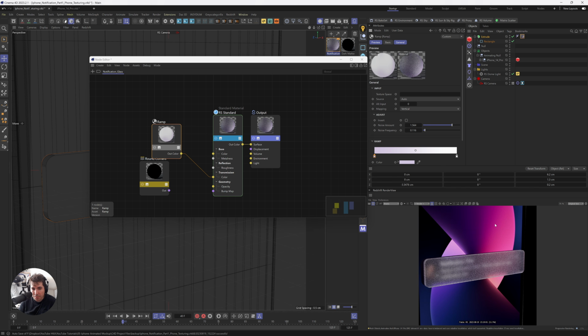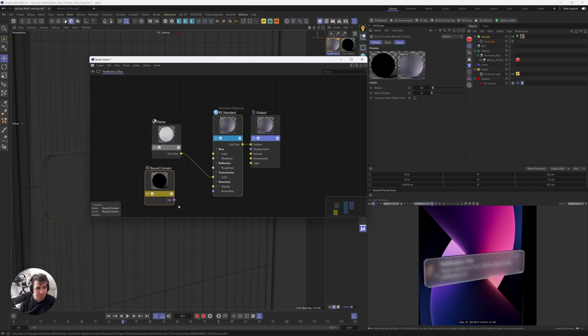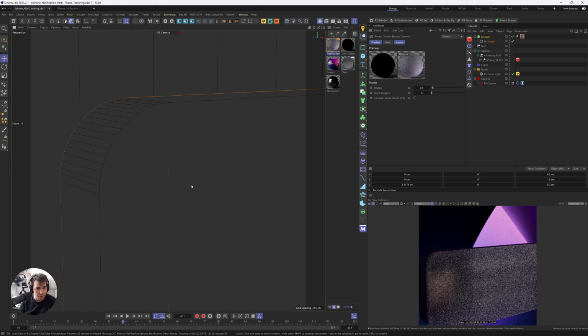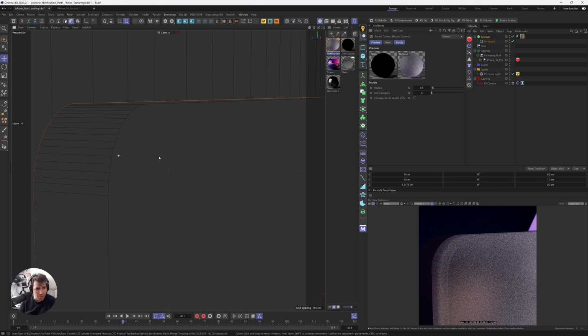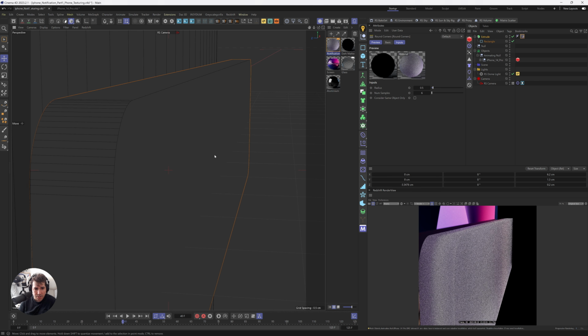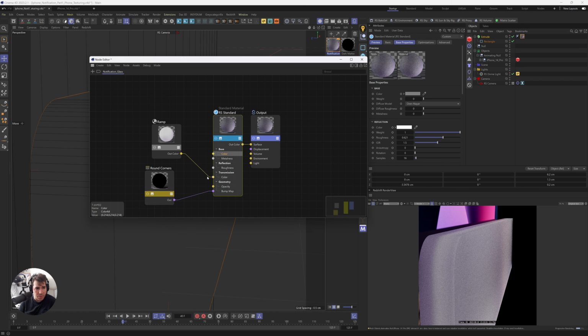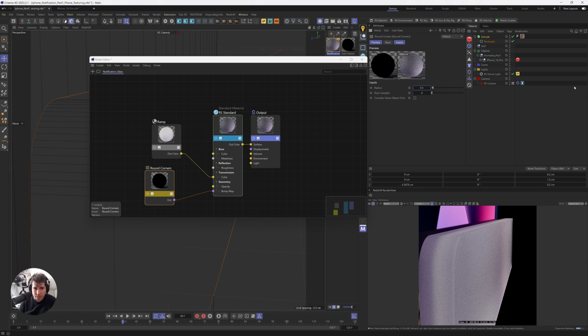So you have a little bit purplish glass, and we can put round corners into the bump map, which will make our notification slightly rounded, and we don't need to do any geometry scaling. So if I look at it from here, I'm gonna see it's a little bit rounded. It's hard to see at this moment, but even better, if you do the settings of the roundness, it works better with the smaller numbers.